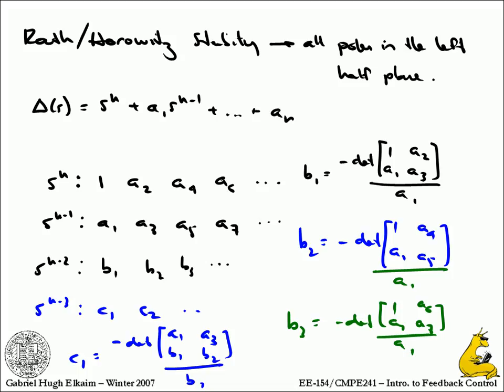Quick question before you go there. It says that if it passes the criterion, then all poles are in the left half plane, strictly? Strictly. So two poles that are on the j omega axis won't pass. Correct. They will fail the Routh criterion.